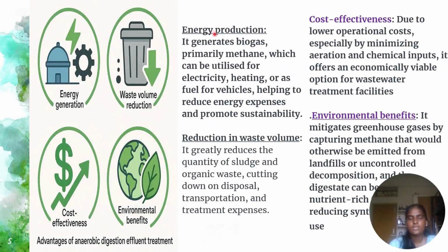Advantages of anaerobic digestion: energy production. In this process, it generates biogas, primarily methane, which can be used for electricity, heating, and fuel for vehicles, helping us to reduce energy expenses and promote sustainable living and reduction in waste volume. And it greatly reduces the quantity of sludge and organic waste, cutting down on the disposal, transportation, and treatment process. Then cost effective, we don't use chemicals and aeration.